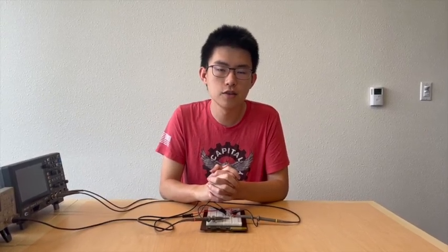For circuit 2, there is a component of a DC. You have two sources. You have your signal generator source, and then you have your power supply source. So your power supply source will actually change how your oscilloscope views the circuit. So that means that you'll have some sort of offset, because if you think back to circuits 1 or 2, you'll see that with superposition, when you add two different frequencies together, you can't do that. You'll instead have two components, and then your DC offset will also be a separate component. So your signal will actually be scaled up or down depending on your source.